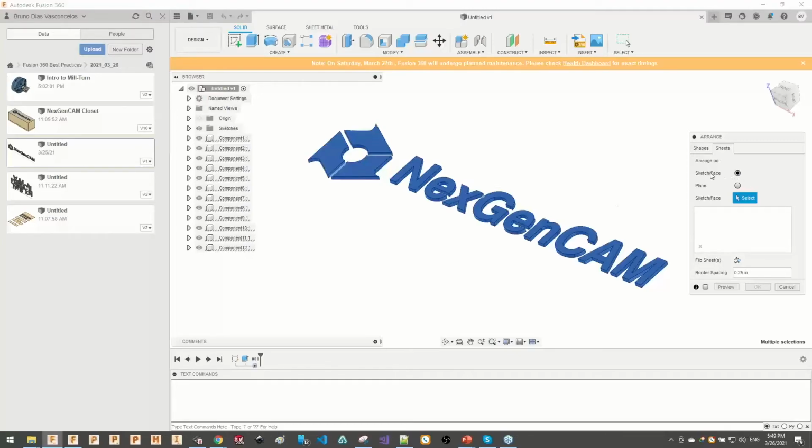So you have several ways. You can use a sketch. You can create your own sketch with your own size, or you can create a work plane. You can not create the sketch, but specify a dimension and a work plane that you want to work with. So I'm going to do plane, and the plane that I want to work with, turn on the origins, is there, and I can specify here, let me see, 36 inches by 96, something like this. Here you specify the sheet margin and the border spacing on the sheet.